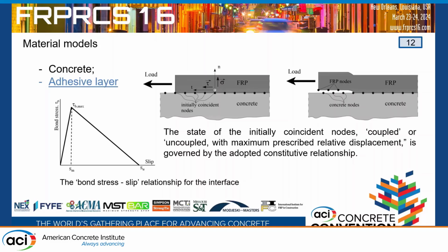But it's quite hard to pull out such a bulk of concrete, because I'm doing about 96 debonding tests with single shear lab tests, and they only attach a few thin layers of concrete substrate on the FRP after debonding. So in this case, it must be easier to pull out some concrete attached to your FRP, but not too much. Here the focus is to properly define the constitutive relationships, to use them further in more complex systems.